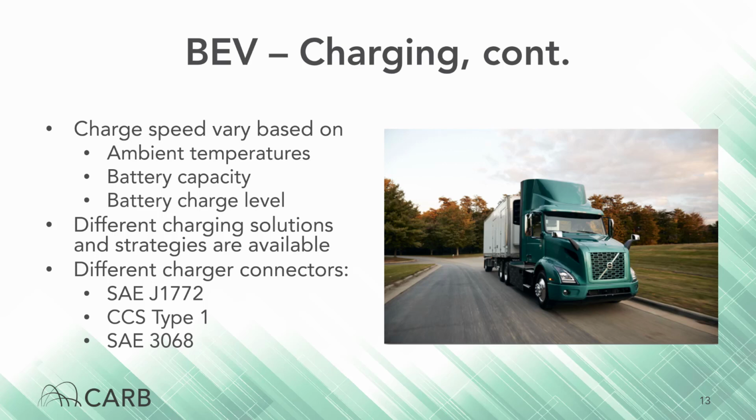Commercial BEVs can also be charged at privately owned power sources, which could be a garage at a residence or at a facility's parking lot, known as depot charging. They can also be charged at a public power source or charging station. This strategy usually involves charging a BEV in the middle of a vehicle's route using a DC fast charger, usually ending the charging process before the battery is completely full.